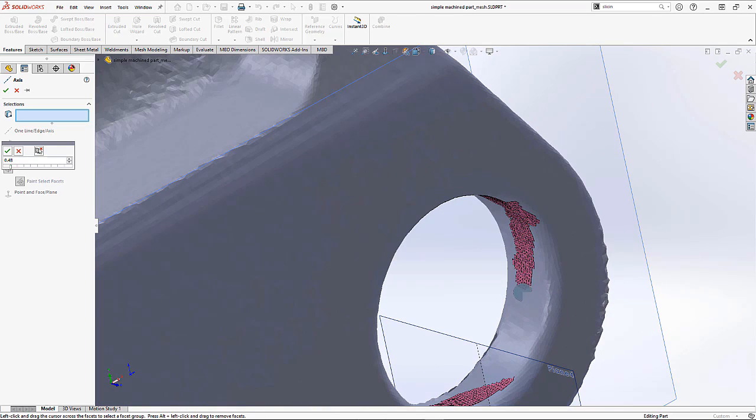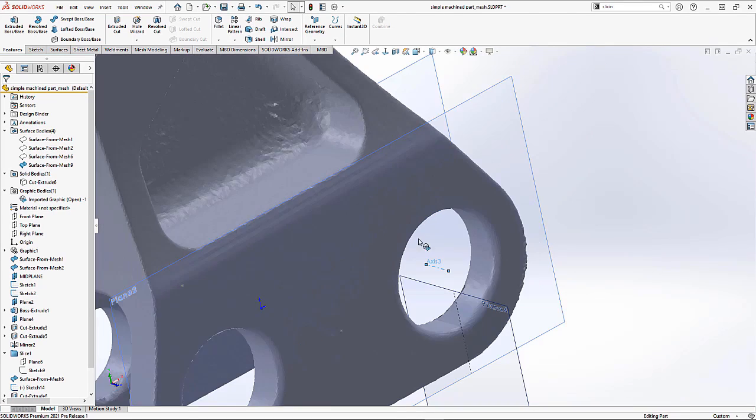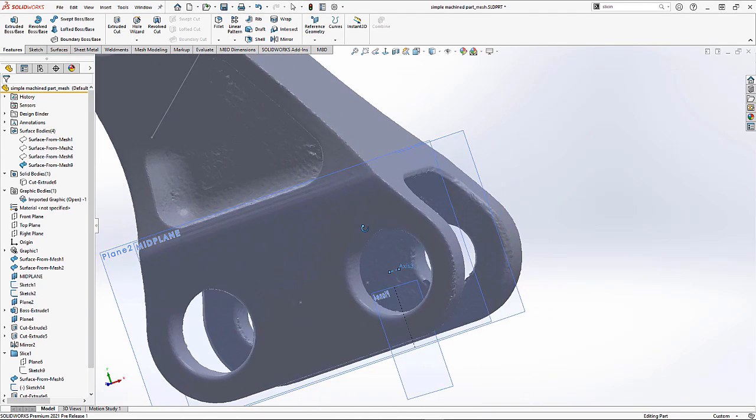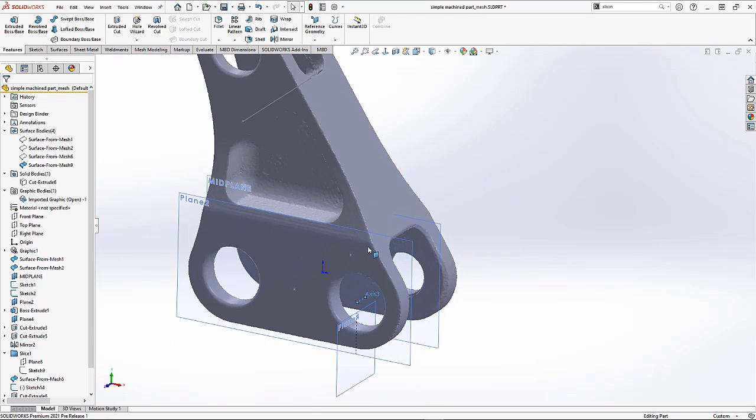We've got the ability to create an axis fairly quickly this way. Now the problem here is each of these options may not be exactly perpendicular to the geometry that we've created. Remember how we had the 0.13 and the 0.14 angle? So those may not be the safest to use unless we're just using them to locate the centers of our circles. So let's take a look at another option.